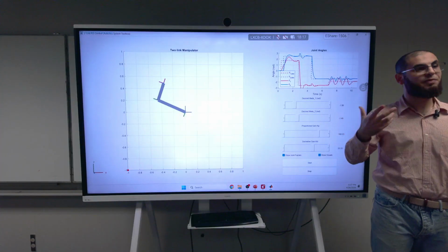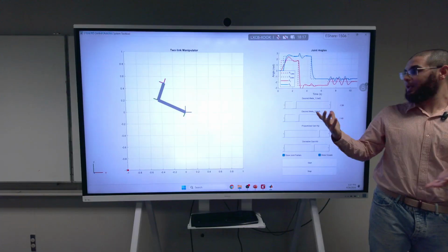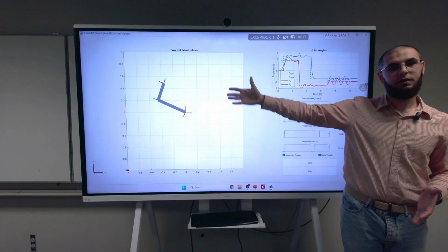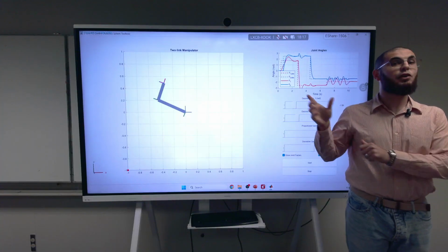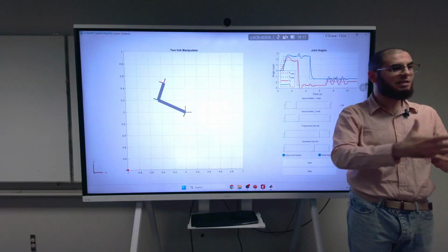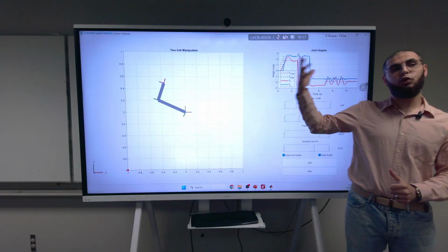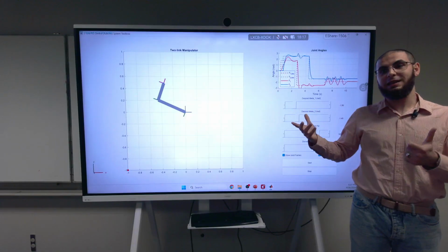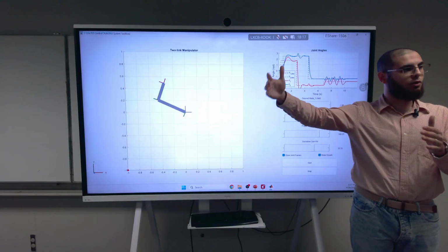It becomes very intuitive to go to the experiment and look at the thing, and imagine that there is a spring there. Imagine that there is a damper and you're tuning the spring and the damper. Even if you have something very complicated like SE3, you can still imagine there's a spring and a damper and you're playing around with them. And this idea of looking at the PD controller as a spring and a damper goes way beyond just doing control. You can even extend it to a lot of scenarios.